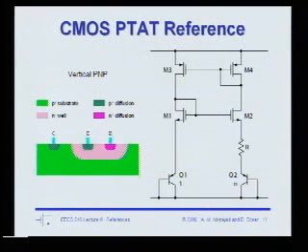So here is, in fact, a way to build a PTAT reference in CMOS technology. The point is that in CMOS we don't have bipolar transistors, right? So if we build bipolars, they're going to be basically N-well bipolars or P-well, depending on the process, if it's a P-well or a P substrate or an N substrate. But what really is unfortunate in a standard generic CMOS process is that we don't really have floating diodes. Every diode we build always has a terminal in the substrate.